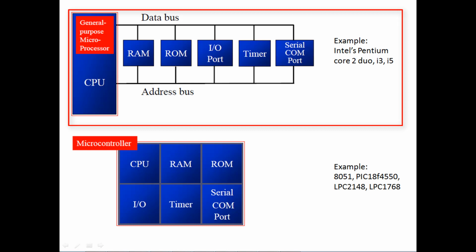Microprocessors find application where tasks are unspecific, like developing software, games, websites, photo editing, creating documents, etc. In such cases, the relationship between the input and output is not defined and they need a high amount of resources like RAM, ROM and input output. The clock speed of a microprocessor is quite high compared to a microcontroller, which operates from a few megahertz to 30 to 50 megahertz. Today's microprocessors operate above 1 gigahertz as they are performing very complex tasks.